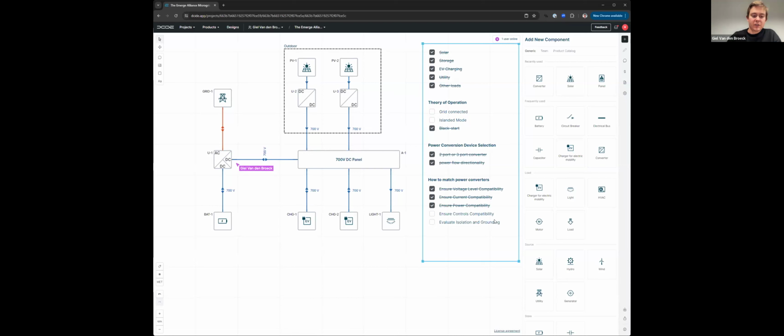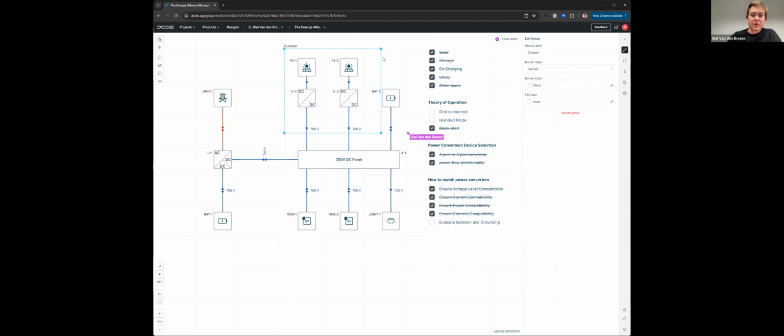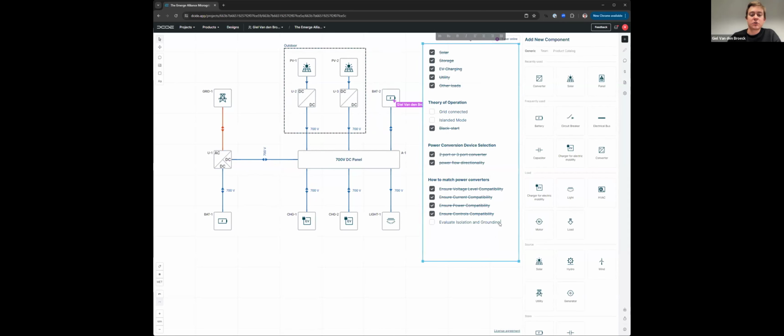So indeed, to continue basically the story of voltage control, let me just give a very basic example. Let's say your central grid connected power converter controls the DC bus voltage in the system. If I now were to connect, let me just drag in a battery to make the case, that battery actually dictates the voltage. It's a voltage source in nature. So actually this battery would dictate the voltage and this converter would dictate the voltage. So the two would start conflicting.